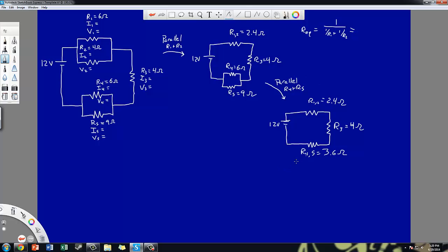Okay. Now, as I had previously mentioned, I can see that I do in fact have 3 resistors in series, and so I'm just going to jump right in and consolidate these in one final step, which should get us down to 1 resistor. So this is series. It's R1, 2 plus R3 plus combined R4, R5. And that gives me 1 battery, 12 volts, and 1 resistor.